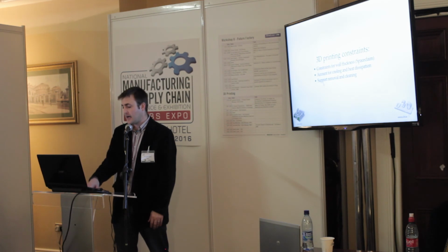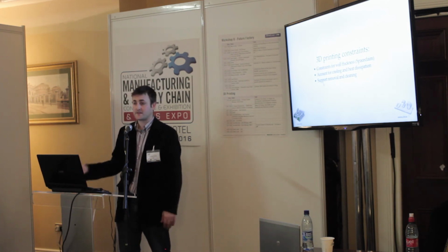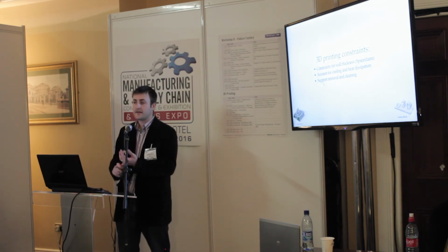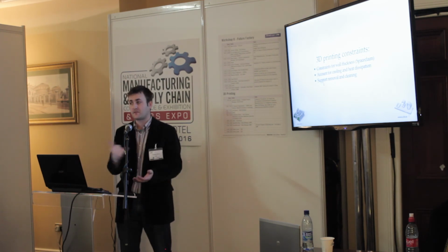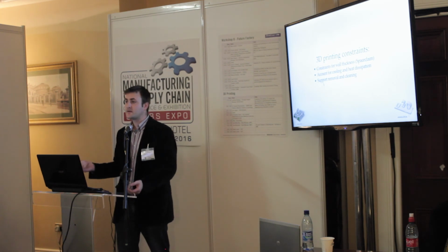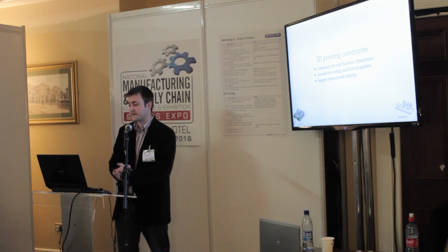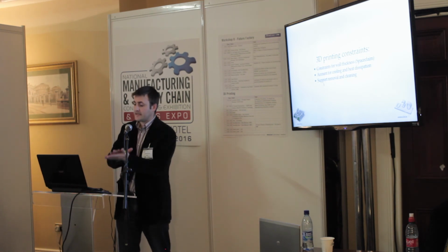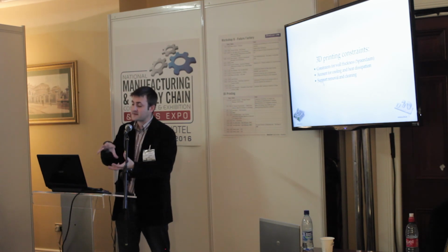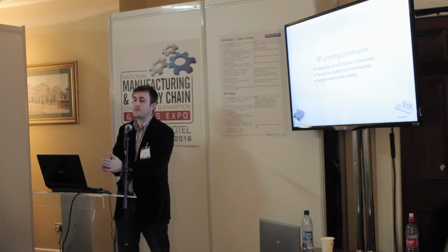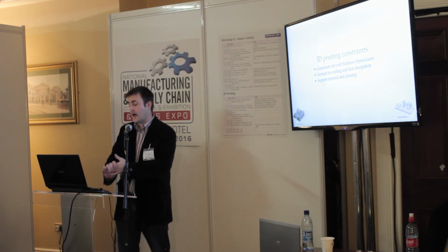And finally, we have 3D printing constraints. These are other factors that can be optimized. So wall thickness: there are limitations in each 3D printing technique for how thick the walls can be and how strong they are depending on the thickness. Cooling and heat dissipation: if it prints too much in one go, it will cause contractions, and there are actually factors in the 3D printing process that can be optimized and have to be accounted for as well.